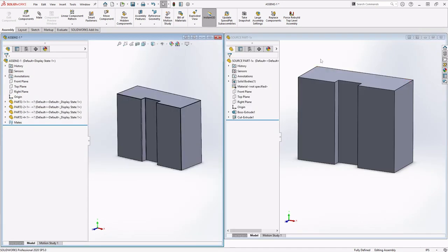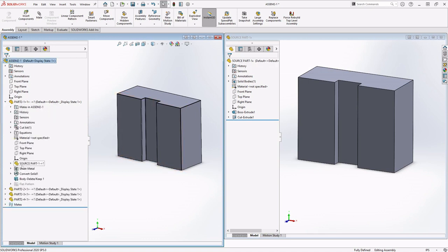Okay. So now what's going on is, even though it's open, these individual fabricated parts right here are still looking for this name. I believe this is the exact same thing that happens even if you're using PDM. If you move the source part around but leave it the same name, I believe PDM will still leave everything linked. But the moment you change your file name, it changes, because it's not looking at an internal ID, just a little technical info. It's looking at the actual file name. So if your file name changes, it won't be able to see it, and it has to update.